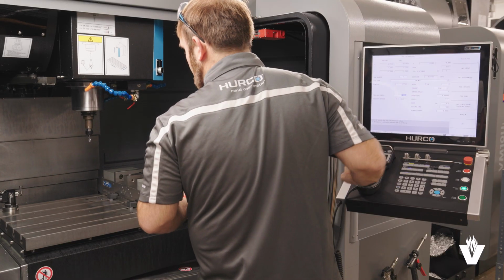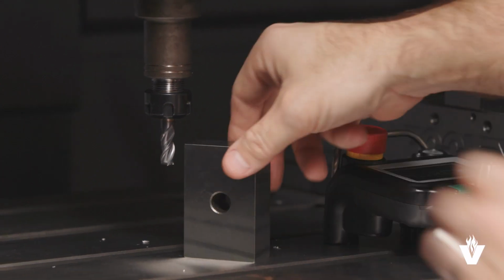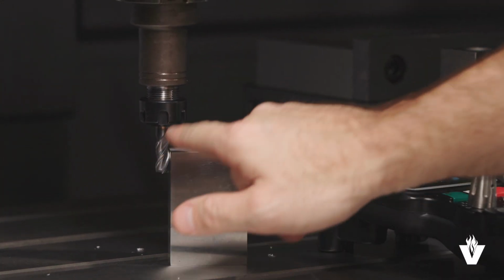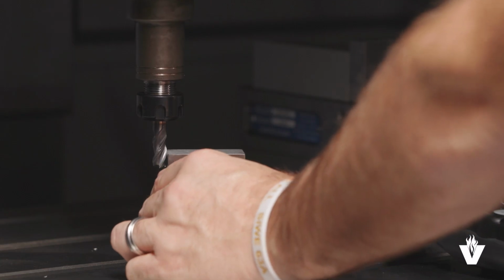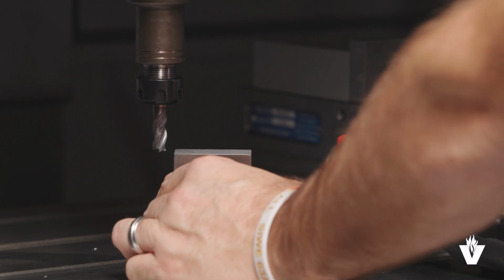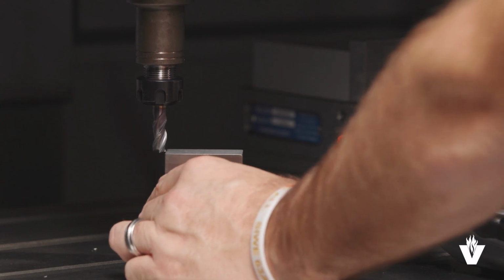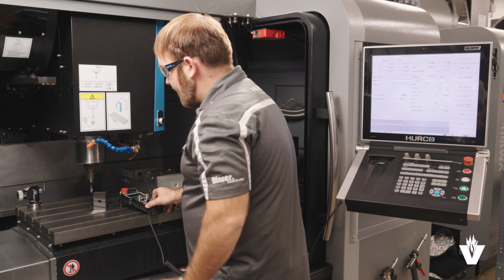With the 1-2-3 block out of the way, we will lower the tool tip down in Z until it is below the top of the block. Careful not to make contact while moving down, as this could cause our carbide tooling to shatter. Now, we will begin moving back in the positive Z direction until the block slides under our tool with no interference.